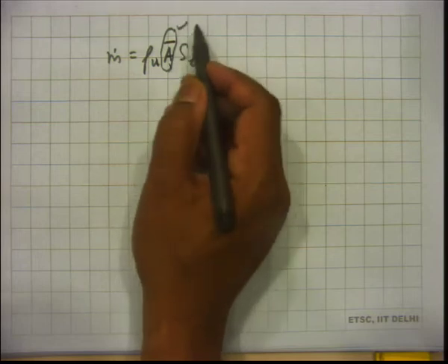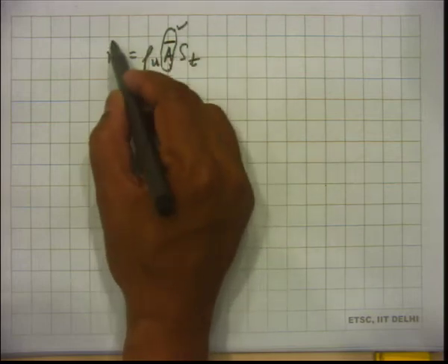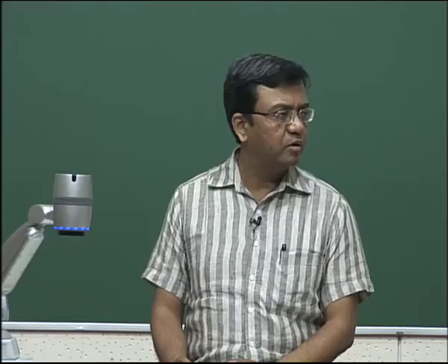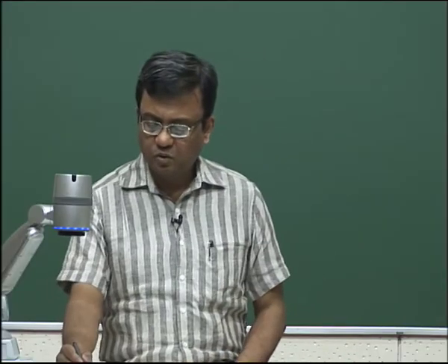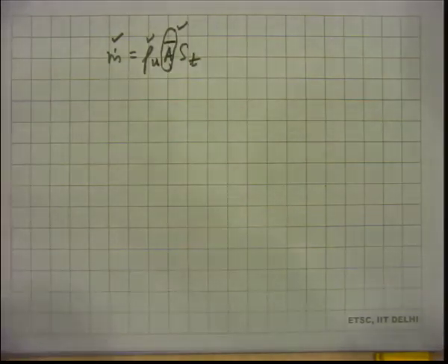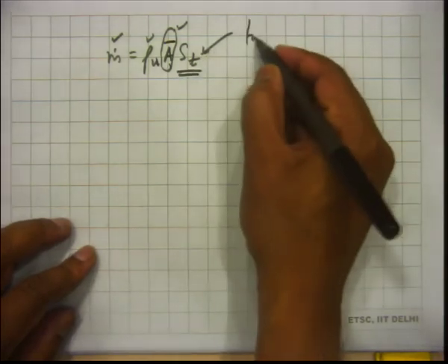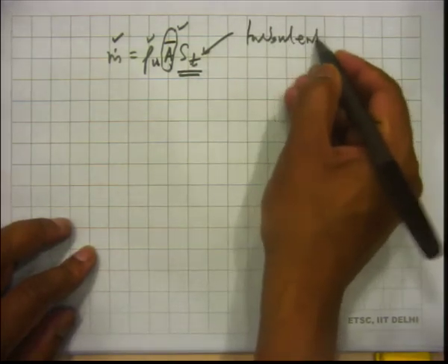So, we can get A bar, and then getting m dot may not be such a big problem. If you are doing an experiment, you are sending some m dot through a tube, and you can get that m dot. If you get that, rho u is easy. In fact, it is the easiest, and from that you can get St. St we are calling the turbulent burning velocity.